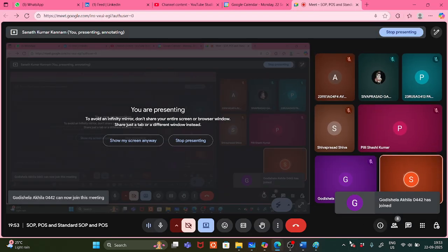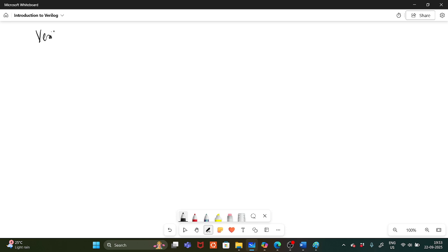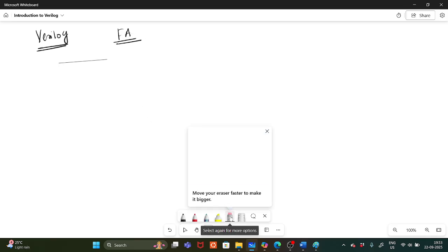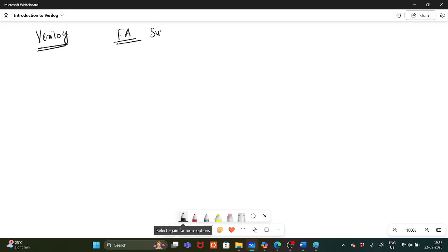So why are you using Verilog? First, suppose you have a full adder circuit. What does a full adder circuit consist of? You know that sum equals A XOR B XOR Cin, and carry equals AB plus BCin plus ACin.